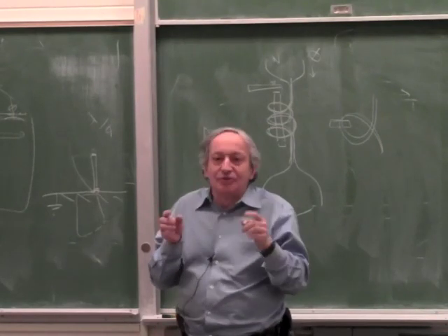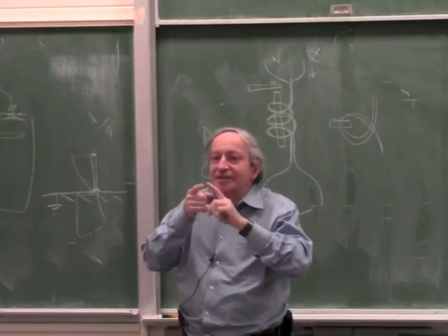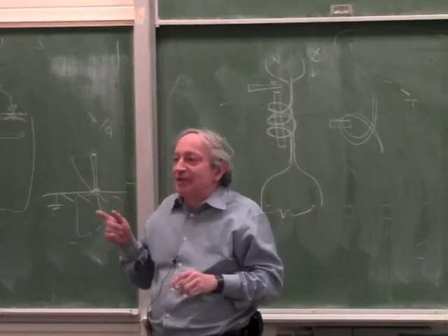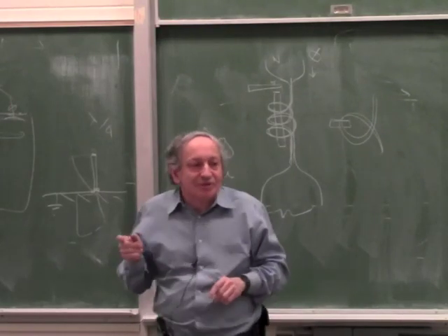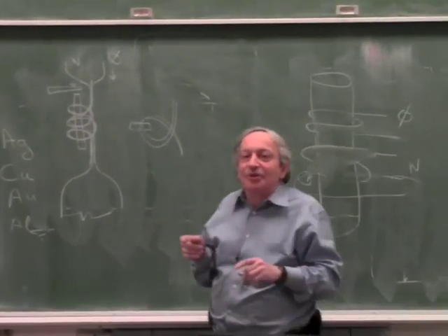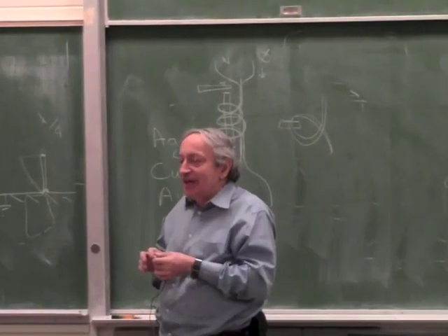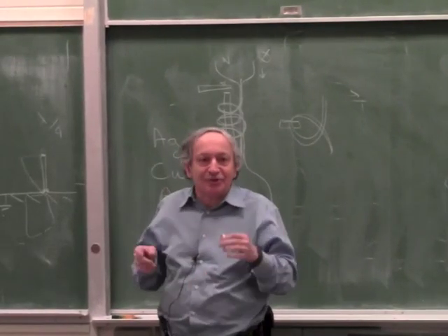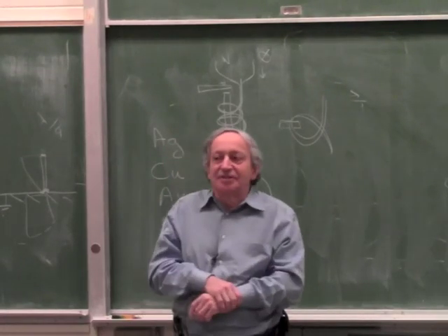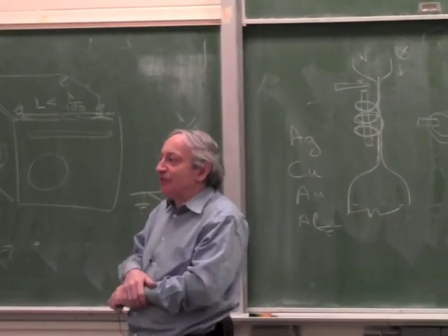So if you just take two wires and touch them together with no pressure, even two copper wires, unless you apply some minimal pressure, say a gram, there would be no electrical contact, because there is some oxide layer, hydrocarbon layer. Now gold is the only metal which at a very light touch gets full contact. And corrosion resistance means it's never going to corrode. Okay? So the second reason is gold is the best material in making good contact at low force.